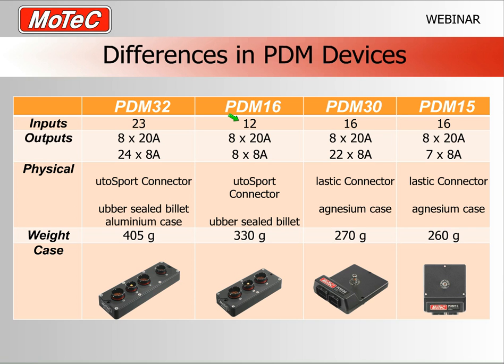And we've also recently introduced the PDM30 and PDM15. They're the devices on the right-hand side. They're in a cast magnesium case with an extremely high temperature coating, and they use the lower cost plastic connector, which you may also find on our M800 ECUs. And this is also an extremely high quality connector with gold-plated pins, but it allows you to get into these devices at a lower cost. They have a similar number of inputs and outputs, and of course the software can be set for any of these devices. So one version of the program will allow you to control any of these devices.